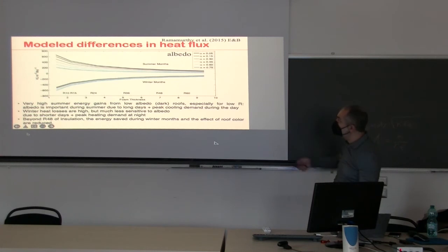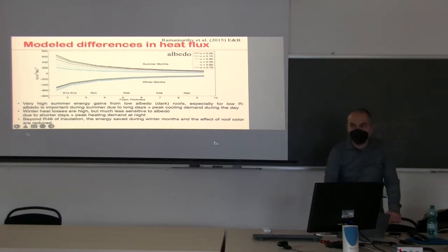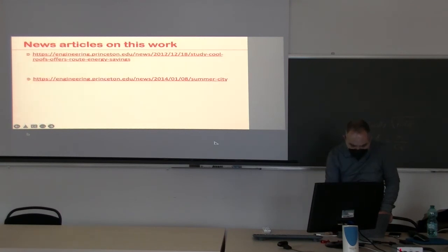As a result, we said that even in colder areas, you might think about using a high albedo. Now, companies don't like high albedo because it can freeze more easily and has more engineering challenges, but in terms of thermal performance, I think with our study, at least I was convinced that this is the case. There are a couple of articles about this work if you want to read a little bit more about it.